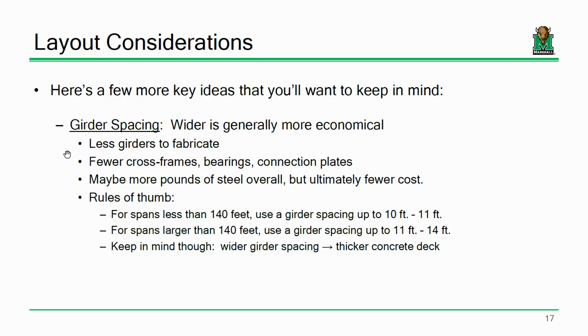So what she mentioned was a concept called load path redundancy. That's sort of a fancy way of stating what happens if you have a bridge and one of the main load carrying elements fails. If you have a bridge that has, let's say, 8 beams, and one of those beams fails, yeah, it sucks, but you've got 7 beams left over. And more often than not, designed properly, you'd think that they'd be able to pick up the slack. But what if instead of 8 beams, you only had 2 beams? One of those beams fails, that's a problem.